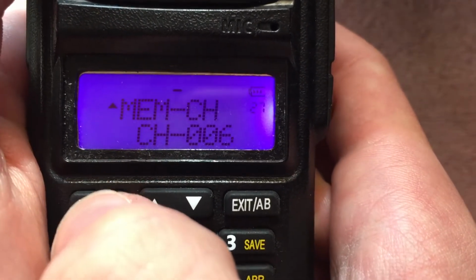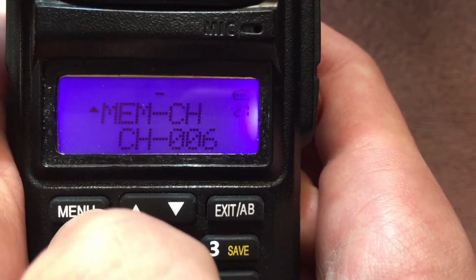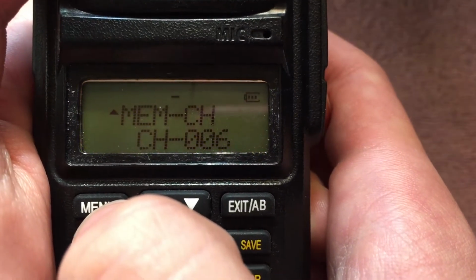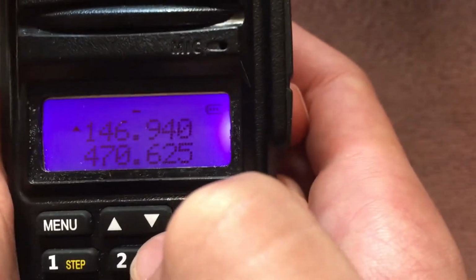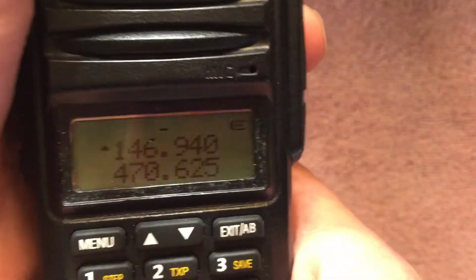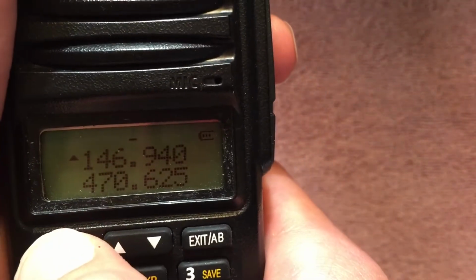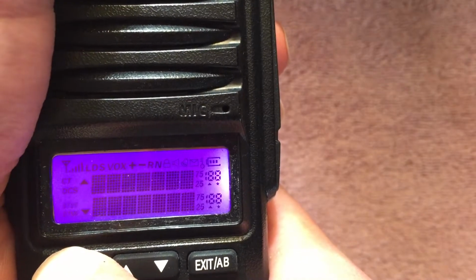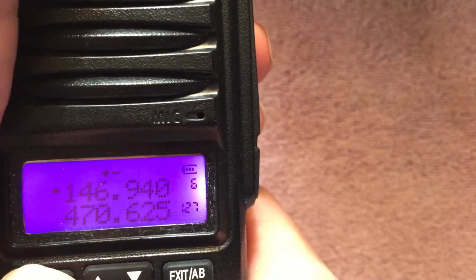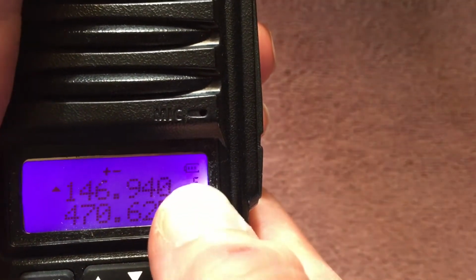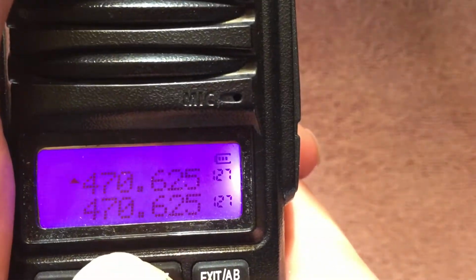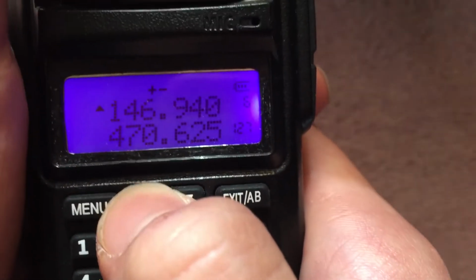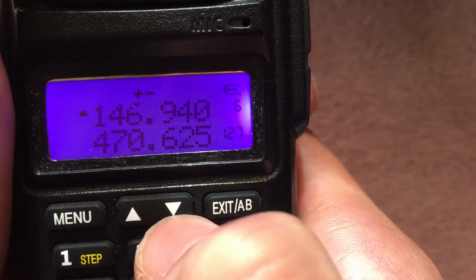Receiving memory. So now you press menu to select it, and that'll program whatever is in the current slot into channel 6. So now you need to switch over to channel mode. Channel mode. Now you'll notice in channel mode it's got these numbers on the sides. And these are the channels. 1 2 0 6. And you can scroll between them using the up and down buttons.